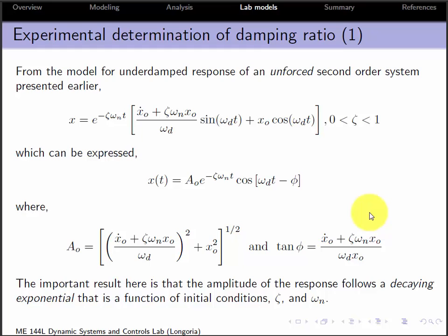The thing to keep in mind is with damping, unlike with a spring, for example, the only way to measure damping is dynamically. With a spring, right, you can hang the spring statically and put forces, statically measure deflection, and you can come up with a stiffness. With damping, you have to have motion, right, because the force of a damper only makes itself known when you've got relative velocity of its ends. If this damper is just sitting still there's no way for you to assess what its damping characteristics are, right?